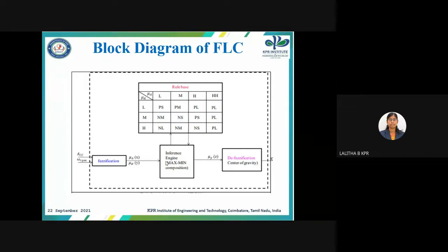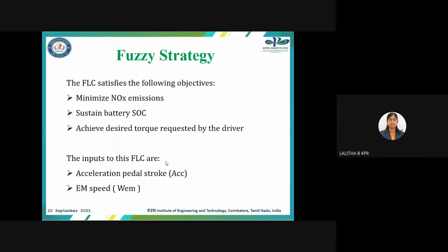In this, the fuzzification process is done. In the fuzzification process, for example, if the IC engine RPM is too low, then inject more fuel. That is the fuzzy value associated with the rule: if X, then Z. The statement would be X less than 2000 RPM. The rule base has a collection of rules; several hundred rules may be developed and applied. The inference applies the defined rules to the inputs. The defuzzification transforms the results of the inference process to crisp outputs. So this is the fuzzy logic strategy which will help to design the controller of the electric vehicle.